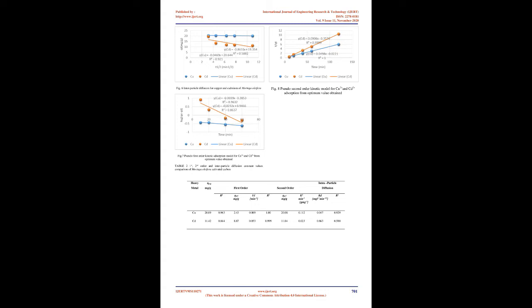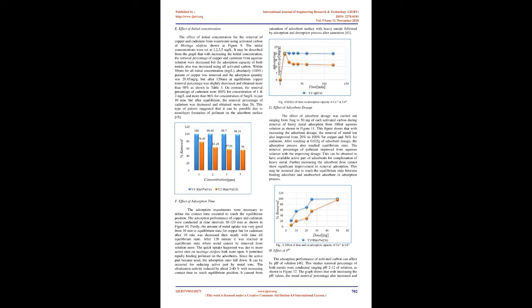Therefore, at 700 degrees Celsius activation temperature, and char, zinc chloride and sulfuric acid with ratio 1:5, the activated carbon showed optimum adsorptive capacity. The results showed a rapid uptake of adsorbate molecules onto the surface of the adsorbent in the first 10 minutes, then slight desorption, and again a slower uptake up to 120 minutes. The reason for this behavior is that the adsorptive sites become loaded as molecules adhere to the surface of the carbon structure. The values however greatly depend on the equilibrium concentration of the effluent with the adsorbent.